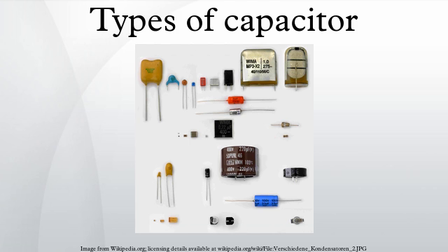End of life, load life, or lifetime can be estimated either by formula or diagrams, or roughly by a so-called 10-degree law. A typical specification for an electrolytic capacitor states a lifetime of 2000 hours at 85 degrees Celsius, doubling for every 10 degrees lower temperature, achieving a lifespan of approximately 15 years at room temperature.